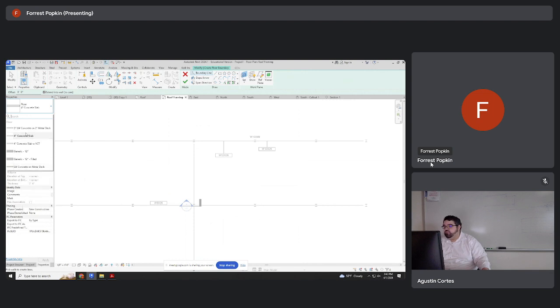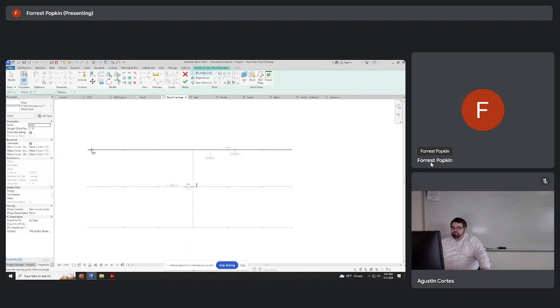Okay? So whether it's a 3-inch or just lightweight on metal deck, the one that looks like a corrugated one in the model would be the 3LW concrete, which is lightweight concrete on a 2-inch metal deck. So if I click that and treat it like I'm doing this for my normal floor, I take the whole structure and press OK.